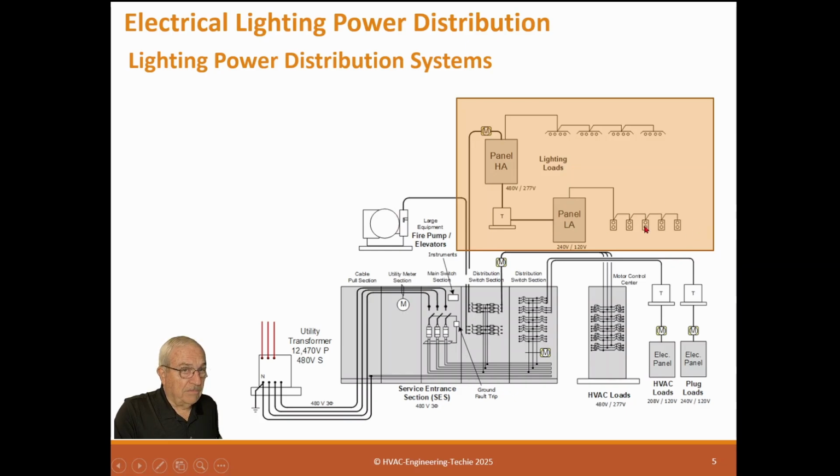And we have these lights in the ceiling that are normally something, well, it might be 277 volt lamps. It'll be up here on this higher voltage, and this may also do the parking lot lights and all that stuff. And that means that by one meter right here, we can meter all the lighting in the facility.